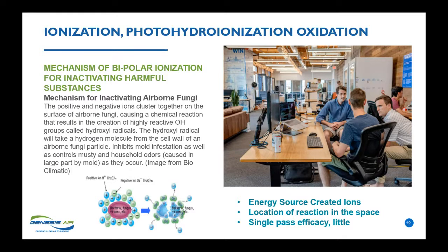So the fellow that's sitting there with his elbow on the table, if the claim is we can kill a mold spore on that table, that energy that was required to create the free radical that killed the mold spore is also available to have a reaction in the lung tissue of that fellow and everybody else in the room. So remember, ionizers work, but are free radicals safe for people to be in that space? So an energy source that creates random reactions in an occupied space is something you might want to consider before you do.